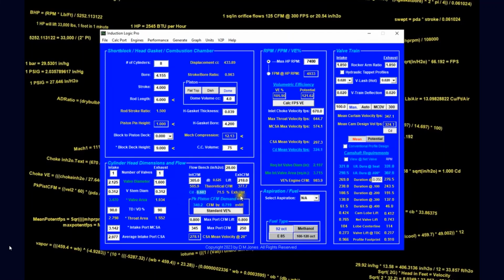This is the net valve lift at the degree of maximum piston velocity of the cam requirement that is currently displayed on the screen. But this is the unadjusted camshaft requirement. So we will stop here and come back to this. At this RPM, our intake valve diameter and valve area is less than the calculated required valve diameter and area. This is common in race engines and will affect the performance if the camshaft is not adjusted.